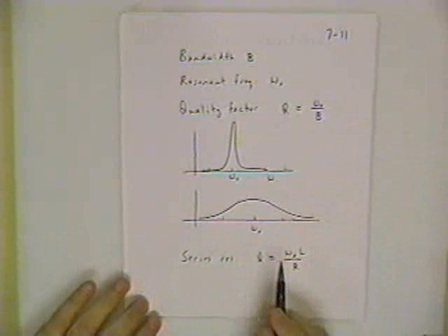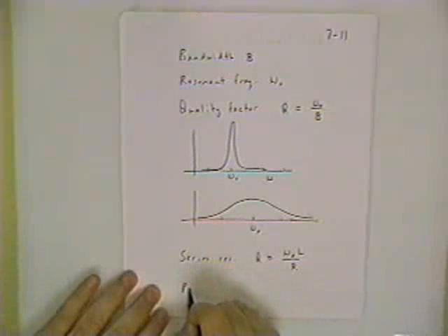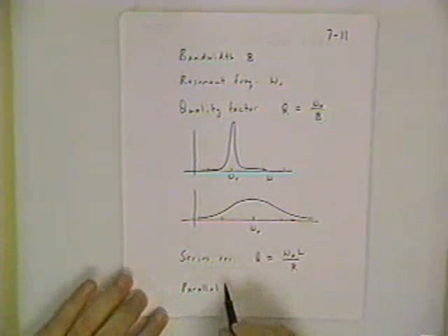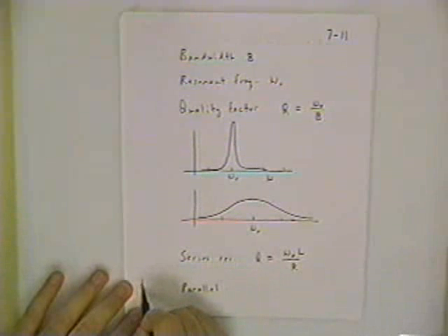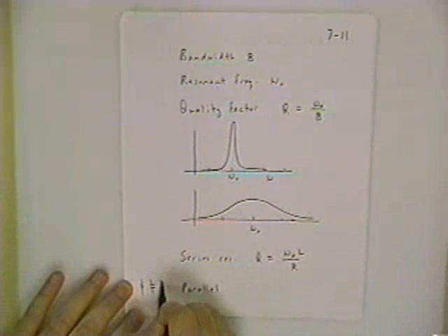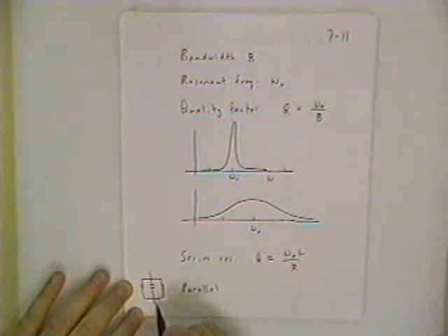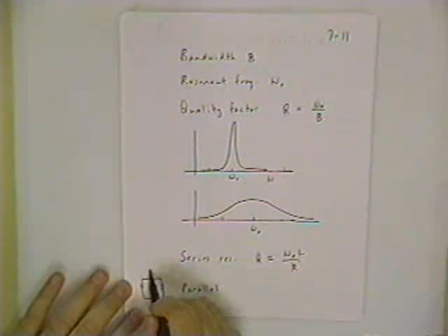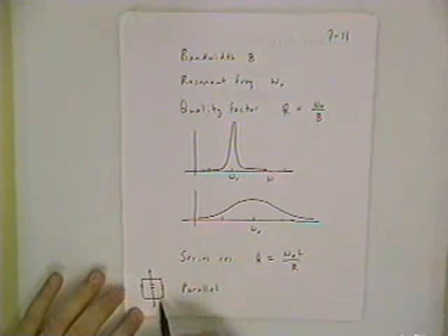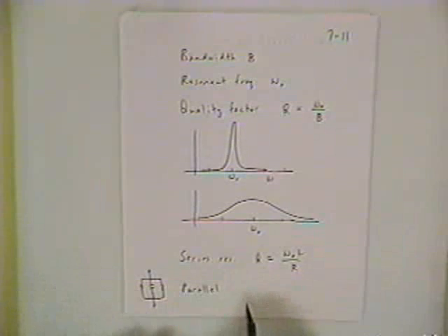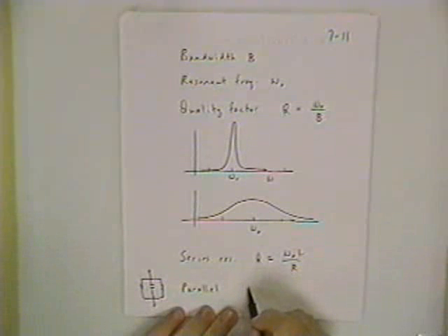Now we can have the same sort of arrangement of parallel connections, and all you have to do is imagine connecting a resistor, in fact I'll sketch it here, resistor, capacitor, and inductor all in parallel, to perform this same resonance function. So you're comparing the voltage applied across these nodes to the amount of current going through it. It'll have the same resonant behavior. The only thing is the quality factor changes.